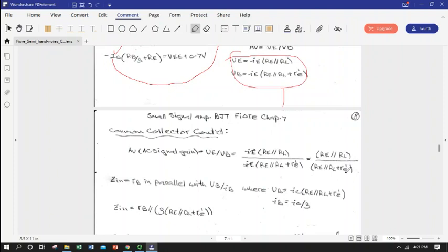So it's like, well, wait a minute, this is supposed to be the voltage follower. It's supposed to have a voltage gain of about 1, and instead of 1, I've got this complicated expression. Well, the thing to remember is R little e tends to be pretty small. The last time we calculated it was about 60 ohms. Depending on how much collector current we're flowing and where we are on that current voltage exponential curve, it can be even smaller than that. So let's assume R sub E, for the sake of argument, is about 50 or 60 ohms. Let's look at the magnitude of this R E R L parallel.